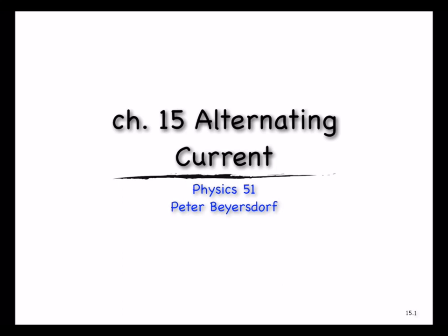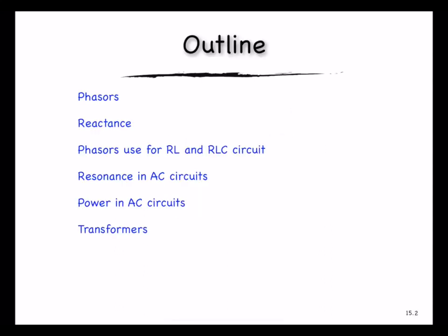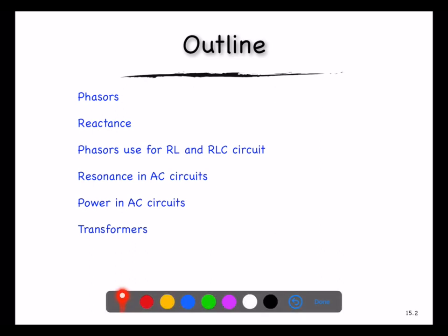Okay, as we generalize our understanding of circuits, we want to be able to deal with circuits where the current and the voltage are not constant in time, are not necessarily exponentially changing like they do with RC and RL circuits, but are actually going back and forth in an alternating fashion. To help us develop some tools for dealing with these types of circuits, we're going to introduce a concept called phasors. Phasors are simply graphical representations of time-varying quantities as vectors.